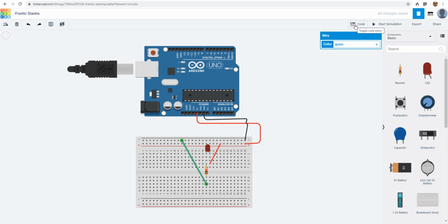In the next tutorial, I would like to create a code such that I like this LED light to blink. So the leg that goes to positive, I'm going to remove this wire. So let's delete this wire that's actually coming to the resistor, coming to the longer leg of the LED. I'm going to delete that. So click on it and delete it. Instead of that, I want to borrow from digital number 3.